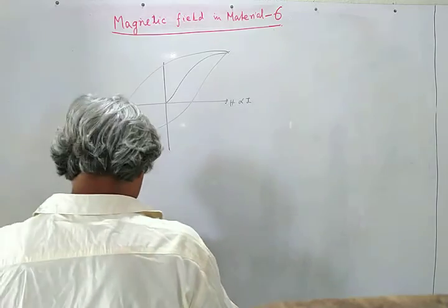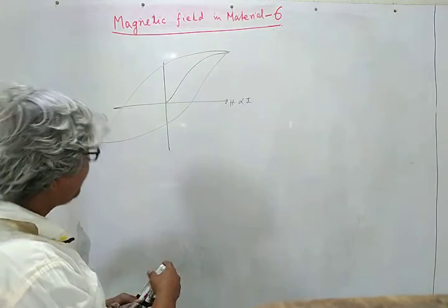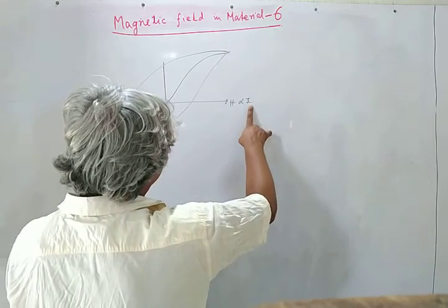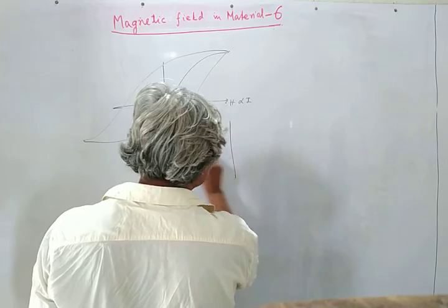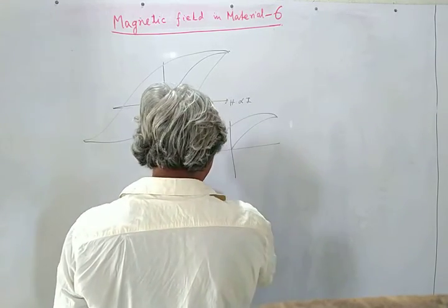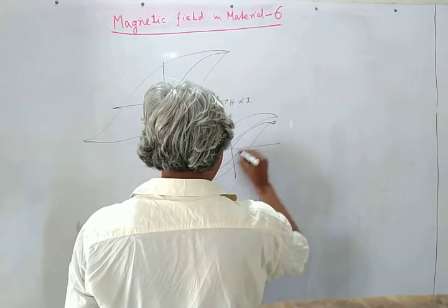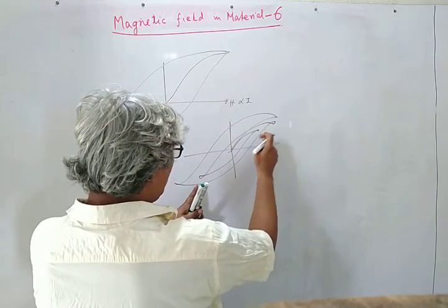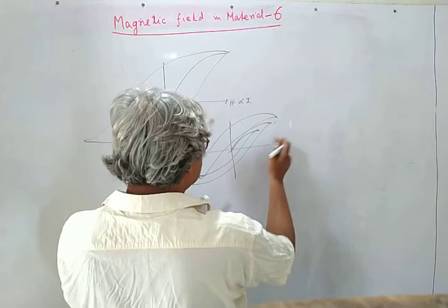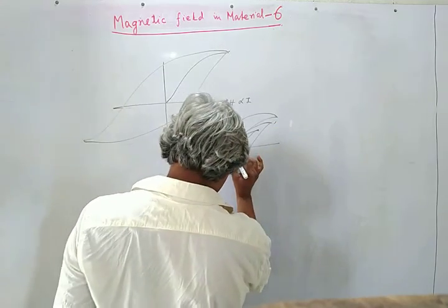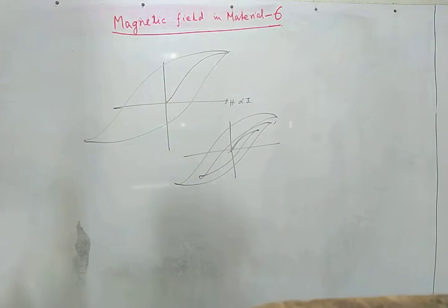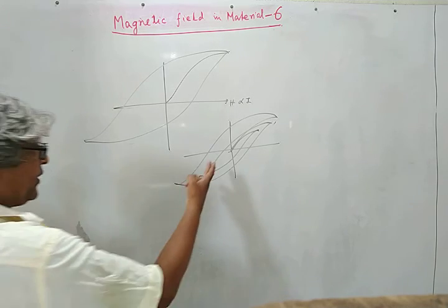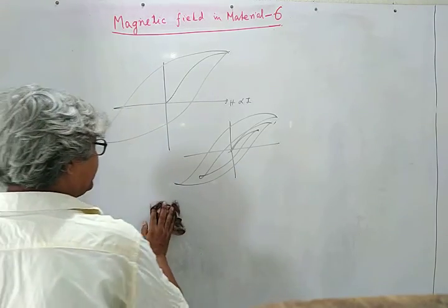If we do this, if we gradually go on increasing I, then the curve that will be traced out is like this. And ultimately, if you go on with a decreasing current, smaller and smaller hysteresis loops will be obtained, and finally we will reach a condition when the retentivity goes to zero. This is the proper way of demagnetizing ferromagnetic materials.